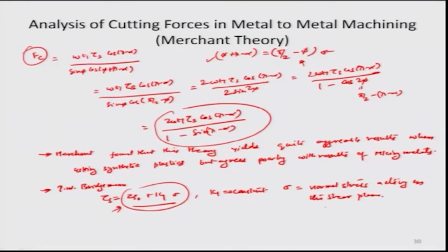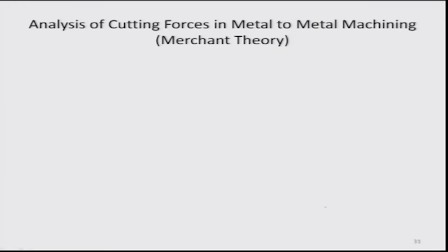And if we look at what those modifications are, so we know that if we just consider what the normal stress is, the normal stress actually is nothing but the normal reaction which is given by the workpiece on the metal per unit area, okay. And actually it is the sine component of the angle phi of the normal force.